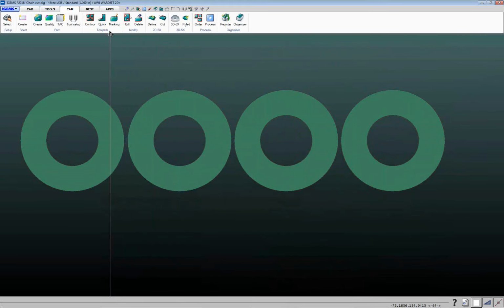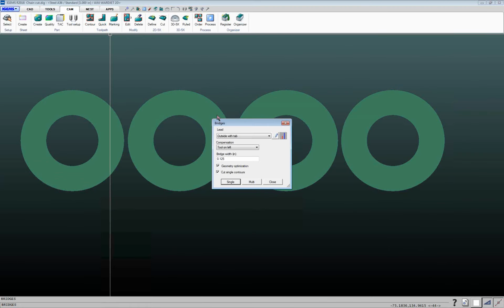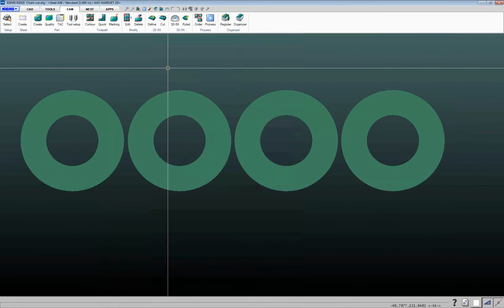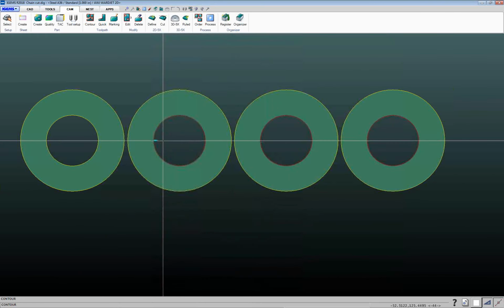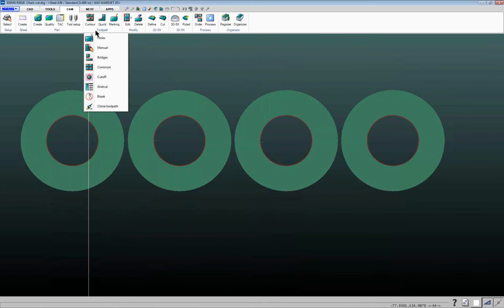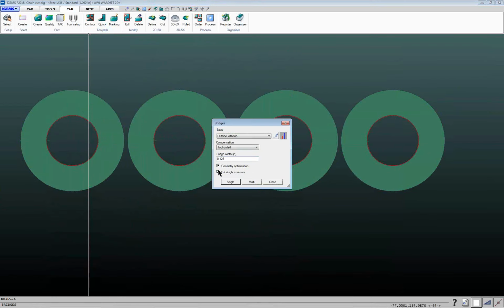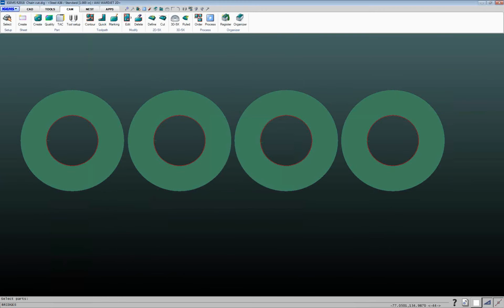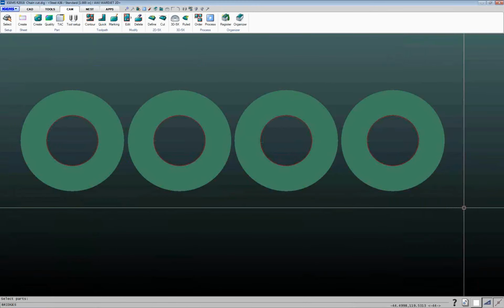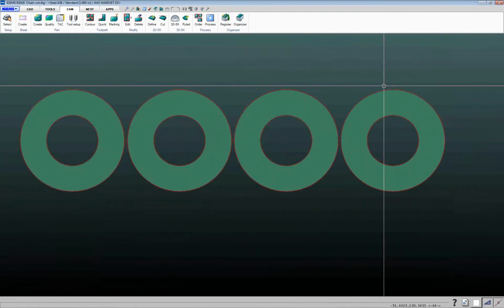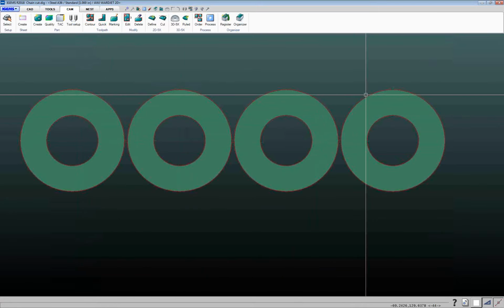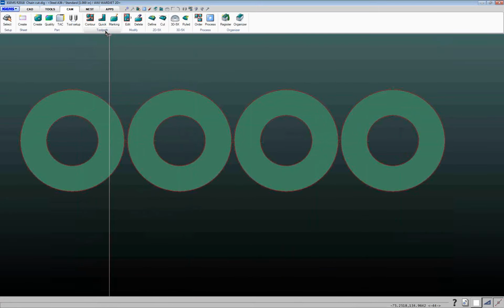So that's that. If we go back into bridges, if I would prefer to have done my own normal single or my normal internal lead-in command, then I can just do it like this, and then come back, go into my bridges command, uncheck the cut singles contour box, and do my multi again. So then in this case, it's going to use what I wanted for my inside leads, and then do my chain cut for my outside cut. So that's one way of doing that.